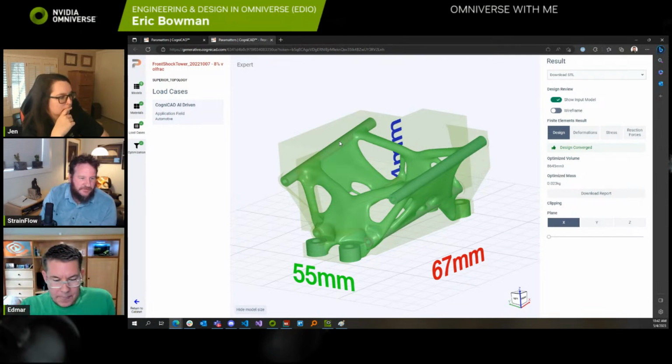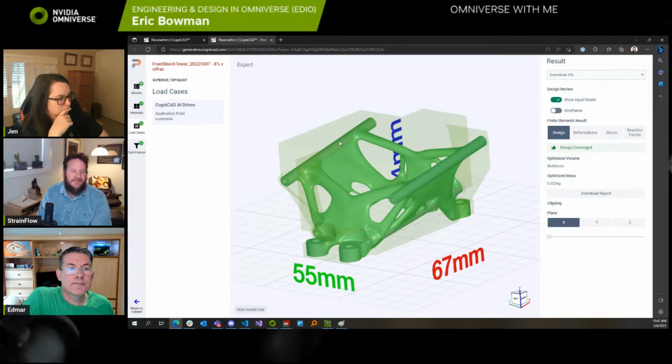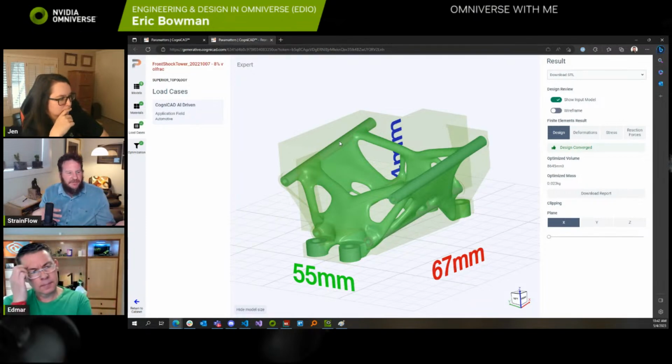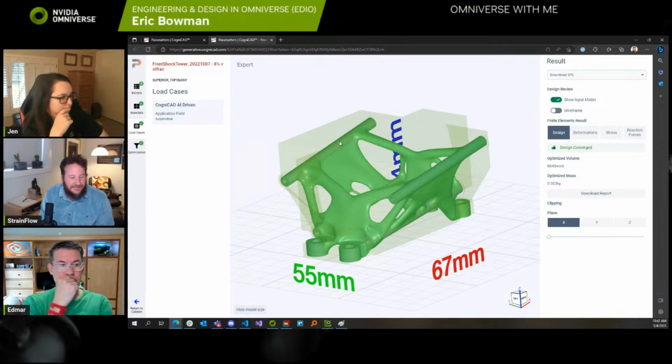And if you can reduce the force, because you're going to have lower momentums, right? Force is equal to mass times acceleration. So if you're accelerating smaller masses, all of your loads reduce, and then you can get improved durability. So if I have a design that's inefficient, it's got extra mass that's not really adding strength, that's just increasing the loads throughout my system, and then I've got to beef everything up to respond to that heavy mass.